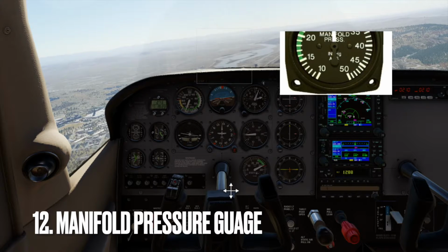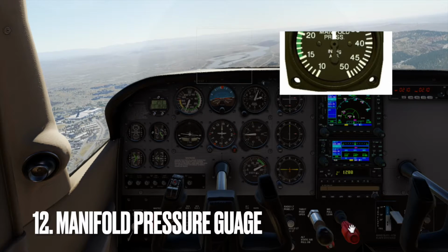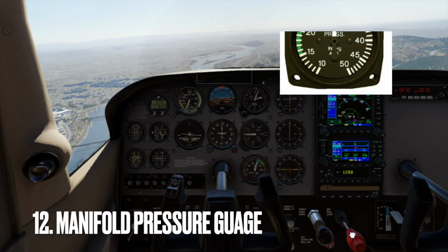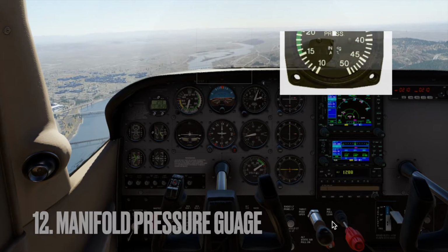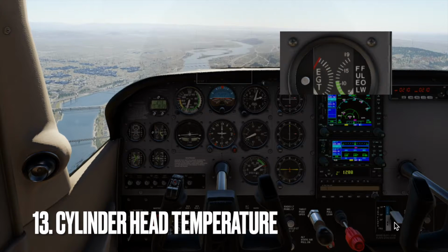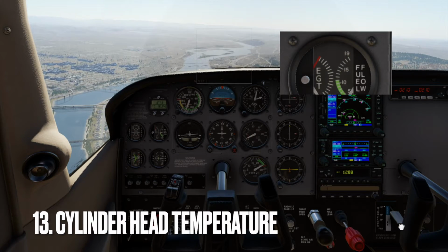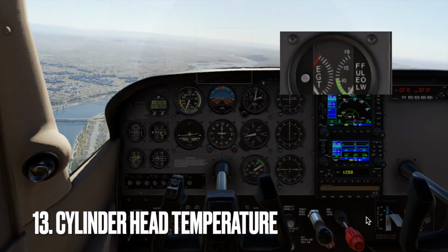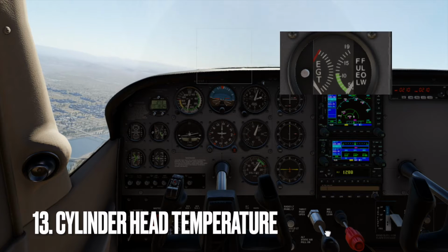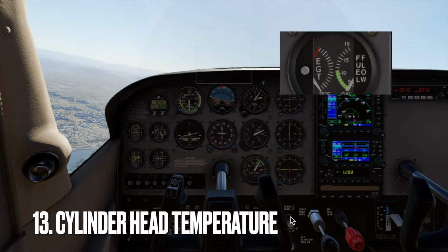An interesting fact about the manifold pressure gauge is that it measures pressure in inches of mercury, inHg, or pounds per square inch, psi, depending on the aircraft's engine system. The cylinder head temperature, CHT gauge, monitors the temperature of the engine cylinders. Pilots rely on the CHT gauge to ensure the engine operates within safe temperature limits and prevent overheating or engine damage.